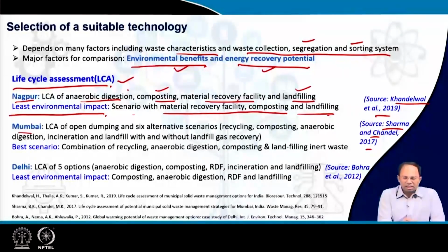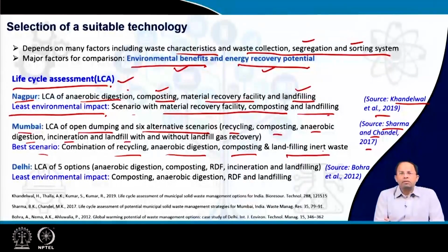In Mumbai, a similar study was done using LCA, of course, where open dumping was compared with 6 alternative scenarios involving recycling, composting, anaerobic digestion, incineration, and landfill with and without landfill gas recovery. So we can just have a landfill or landfill with gas recovery, that was considered. Here the best scenario was found to be a combination of recycling, anaerobic digestion, composting, and landfilling inert waste. So this combination was found to be the best one.